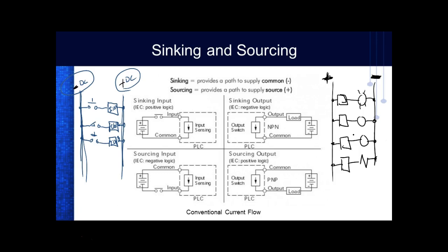So when I go out and buy a fixed PLC, usually this is defined, except for Allen Bradley. Allen Bradley splits the inputs up and usually splits the outputs up, so you can configure in groups. You can't mess that up. So we okay? So normally your inputs are sinking and your outputs are sourcing if you're dealing with DC.